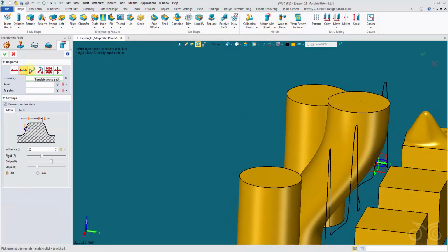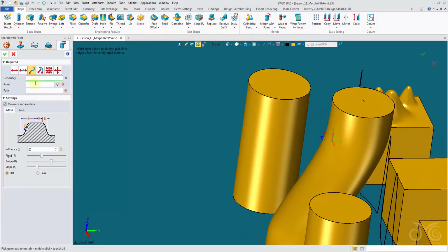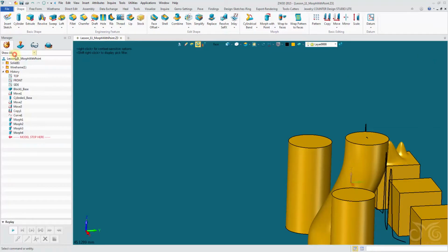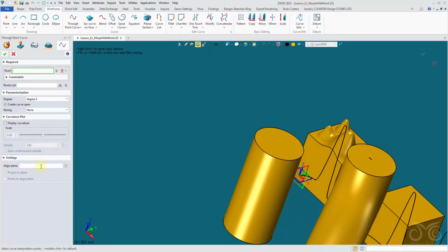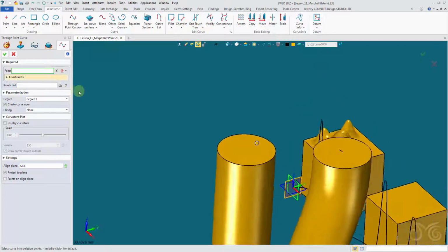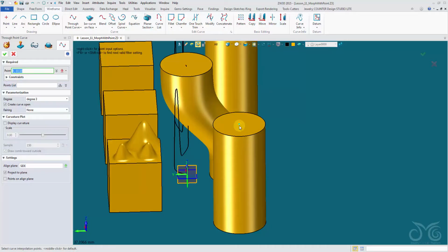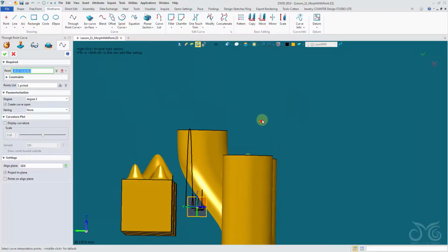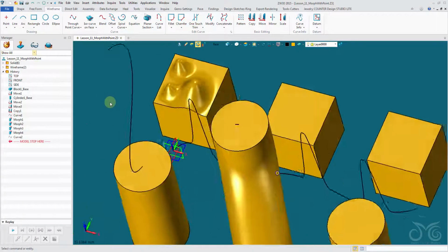Next, let's look at our translate along path. This time a point on our geometry will be morphed along a path. So let's create a path first of all. Wireframe, 3-point curve. Let's align it to the side datum plane. Come around this side. Let's pick a point, say the center of the cylinder, and then we'll create a curve. Confirm the operation. So there is our path.